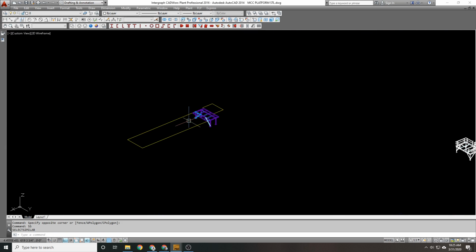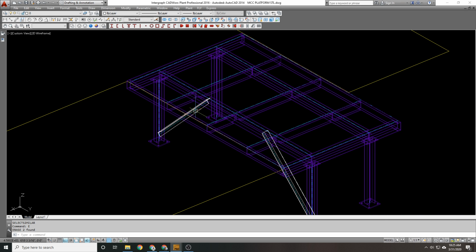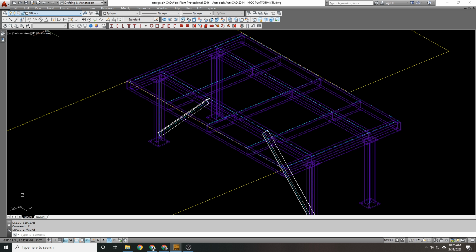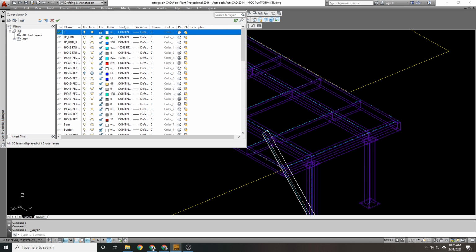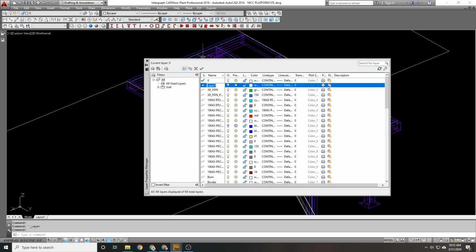I have an alias for that just to make sure I don't have any other lines, which I do here. I can erase that. Before I copy this, I'm going to make sure I don't have the layer set. So I'm going to create a new layer, my personal preference, called VBrace. So I'm going to say new layer. And if this looks kind of silly, it's because I'm using an older version, AutoCAD 2014. You're likely using a much newer version. Even 2016, I believe, looks different.